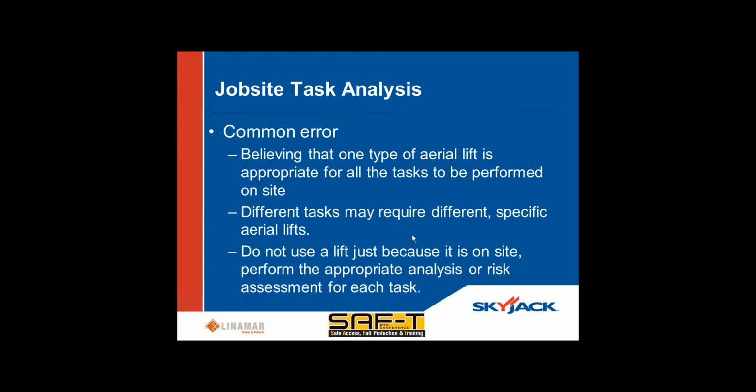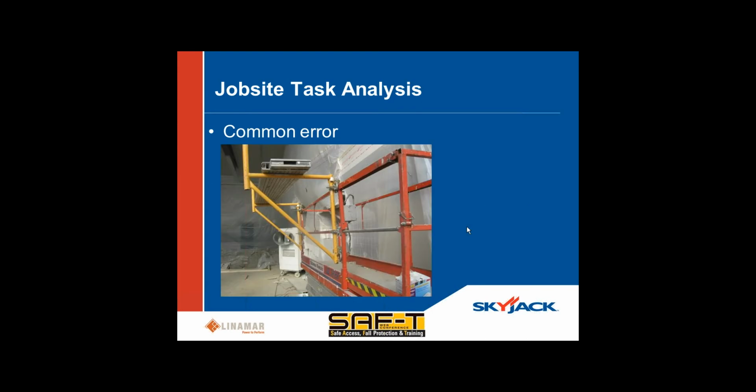Again, I kind of got a bit ahead of myself, but really, don't just use that lift because it's on site. You really have to understand that somebody's taken a look at this analysis and done a risk assessment of the various tasks on site that need to be completed. And is this the right piece of equipment for all of those tasks, or do I need different pieces of equipment for different tasks on the site?